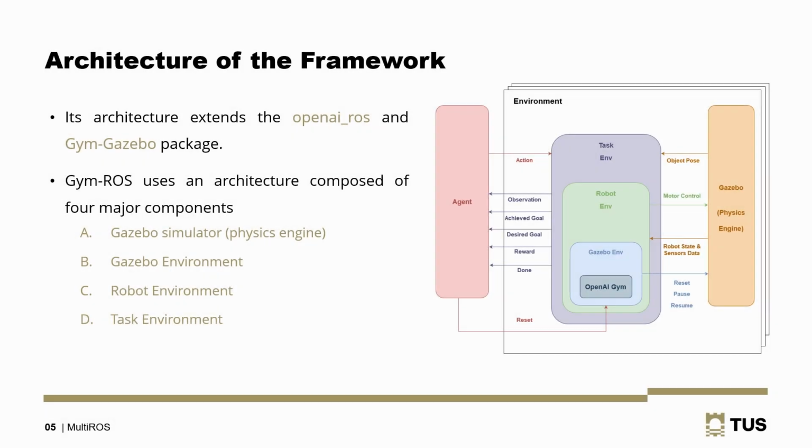MultiROS uses a modular architecture composed of four major components: the Gazebo Simulator, Gazebo Environment Class, Robot Environment Class, and Task Environment Class. The Gazebo environment, which utilizes the OpenAI Gym, is the class that specifies the connection to the Gazebo simulator. It provides the functionality to reset, pause, and resume the simulation.